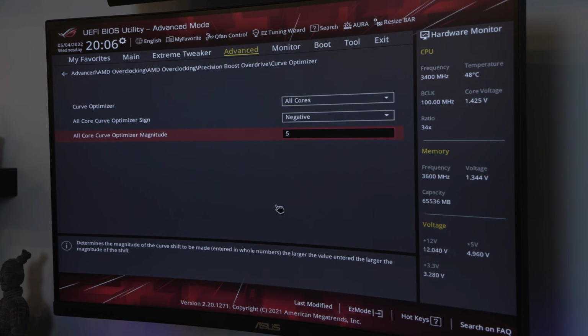I find that a -15 on my 5950X was too high and it would actually crash. So on most of the cores, they're only good to about a -14. I found that on the second CCX on the processor, most of the cores can only do a -9. So depending on your cores, when you're looking at your AMD Ryzen software, you'll see that it has the starred, the preferred cores.